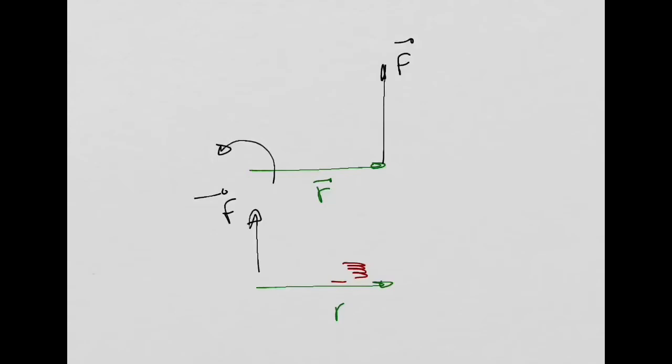Yeah? This seems similar to the right-hand grip rule. Yeah, that's what I'm saying. Thank you for the English correction. That's exactly what I'm saying. Right hand rule. So, the right hand rule is you use your right hand, you align your fingers with the position vector, you rotate your fingers towards F, and then your thumb will tell you the direction of the moment. Z, right? So, that's how it works. Now, let's continue with...